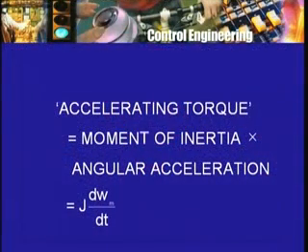Now the dynamical equation for the rotational motion, as you know, is similar to Newton's equation for motion of a particle, namely mass into acceleration is the total applied force. So here then we will have the moment of inertia J multiplied by the angular acceleration, and since we have denoted the angular speed by omega m, therefore we will have it as J d omega m by dt.